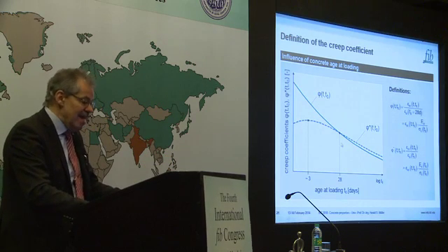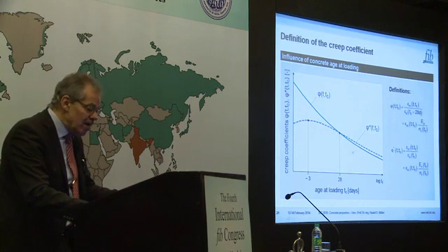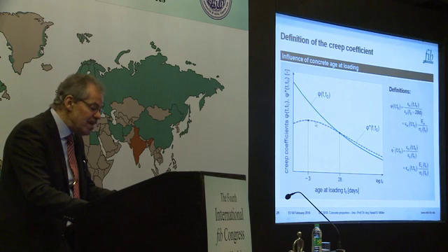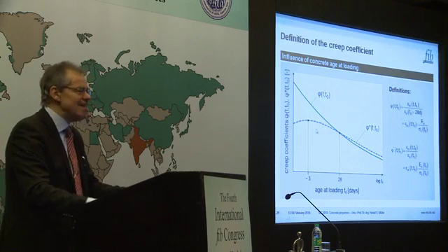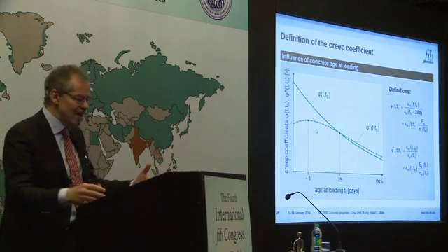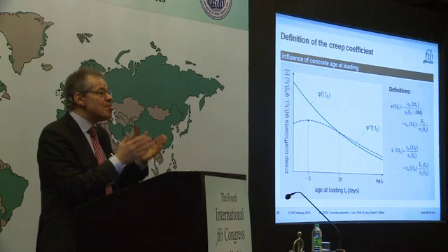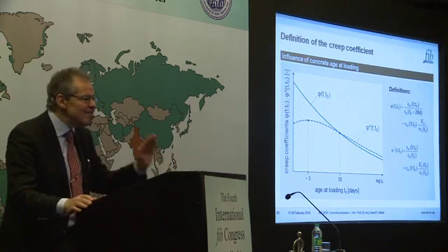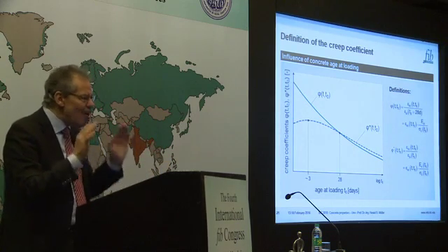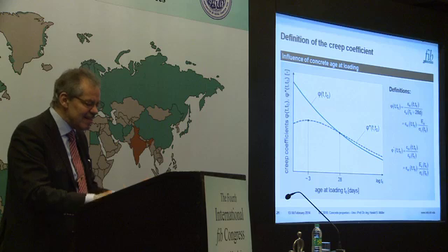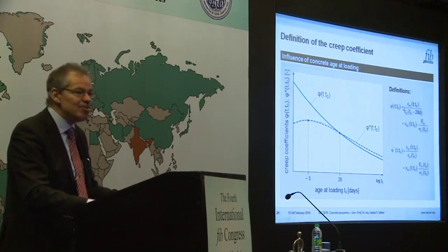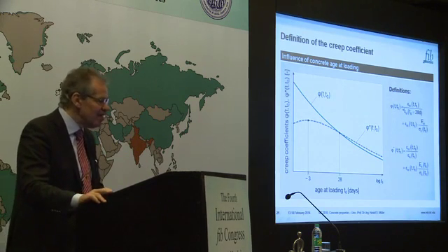But if you reduce the age of loading, you have a maximum for the ACI definition, and then it goes back. But every engineer has a feeling that the creep is the higher, the lower the age of loading. This is only correctly reflected by this type of approach we adopted in the Model Code 90.